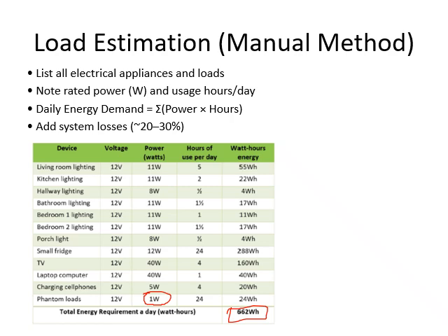But in the next slide you will see that I've used the house's electricity bill for the whole month, and then we can also make it per day. That is also a quick way to get an average if you already have a house installed with the power supply system. You just take the electricity bill and find how many kilowatt hours you have used, so for one day on average, how much would it be?